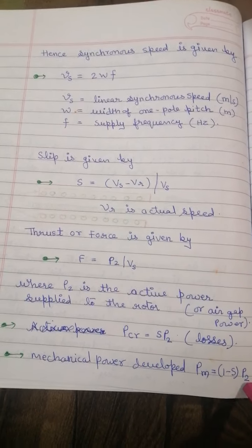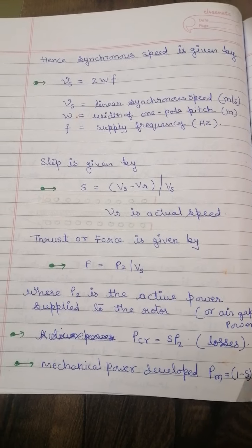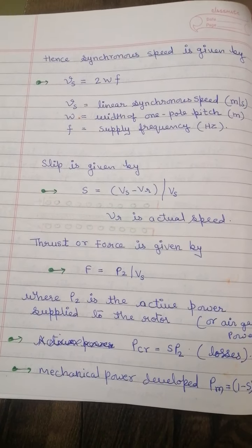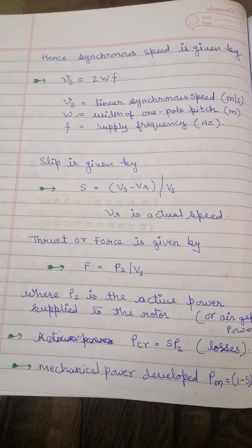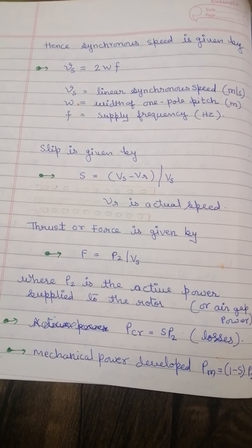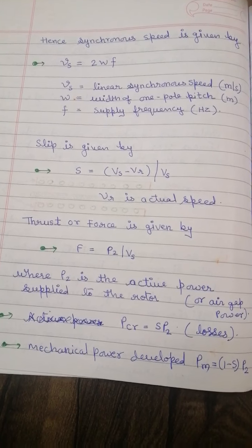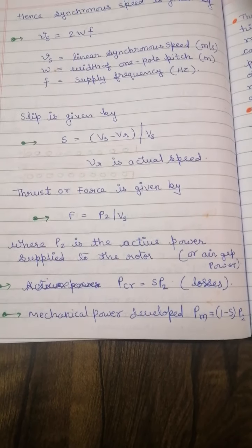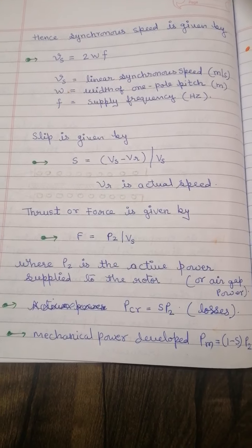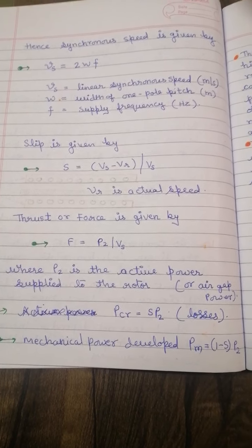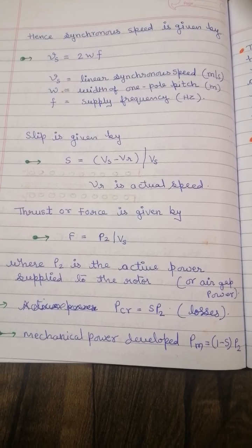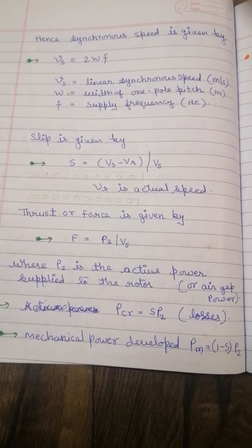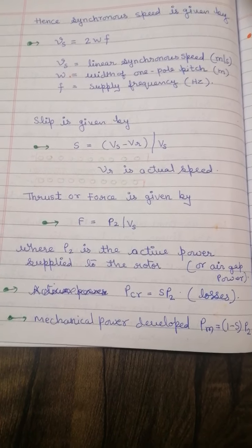So that's all. This is the linear induction motor. And what are the applications of this linear induction motor? The main application is in transportation, including electric traction motors. Especially it is used in electrical traction, where the secondary would be the track and the primary would be fitted on the vehicle. So in a traction system this motor is always used.